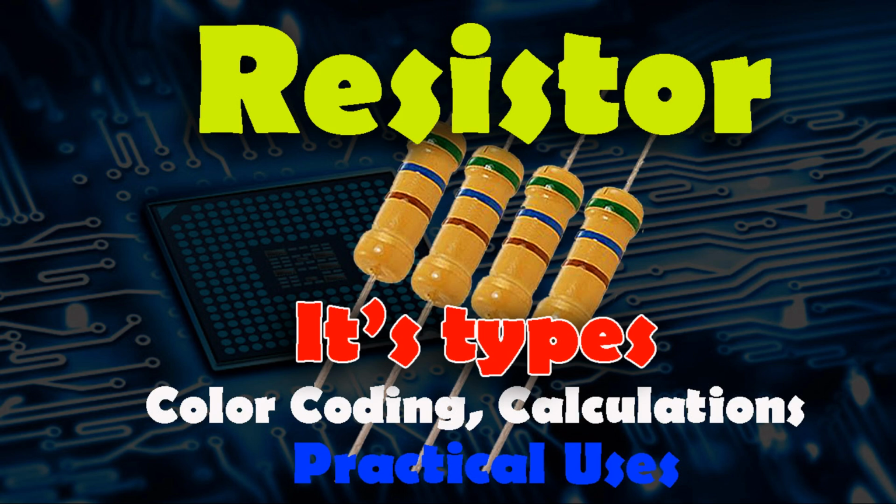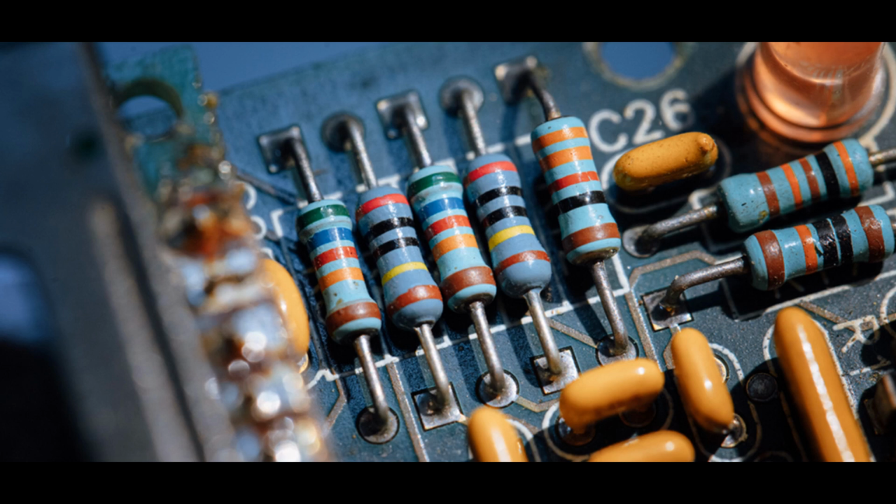Emitter bias, self-bias. Description: a resistor is placed in the emitter lead, providing negative feedback to stabilize the operating point. Advantages: good stability and simplicity. Disadvantages: the need for a large emitter resistor can reduce gain.